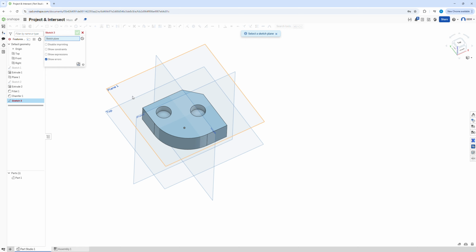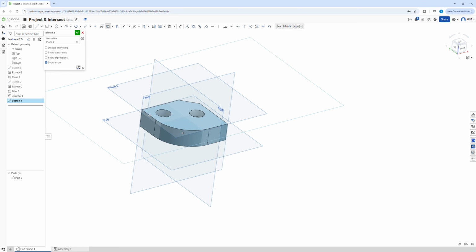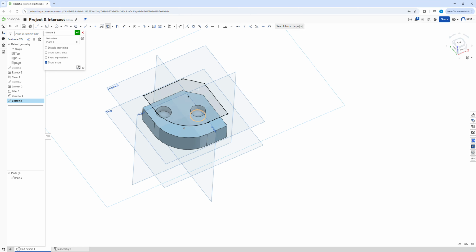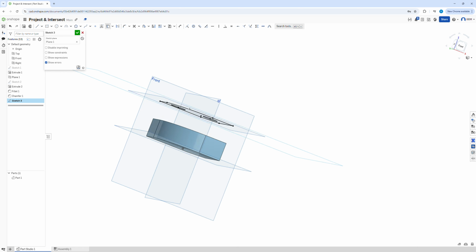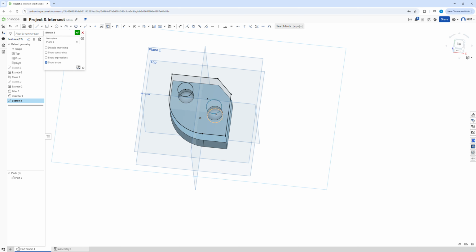Now in terms of using, if I go into my sketch tab, let's choose this plane that I've added. Up here we have our use tool, so I can click on there, and rather than re-sketching all of these things, I can click on this top face and that will project that up. I can click on this circle, and now very quickly I have my part fully constrained. If I want to see how the constraints are, we can see that as well.